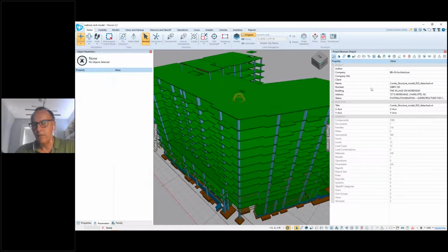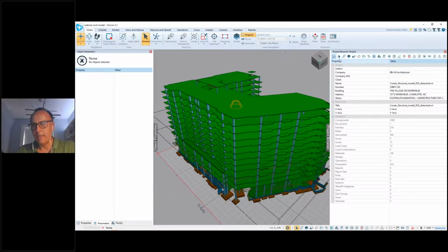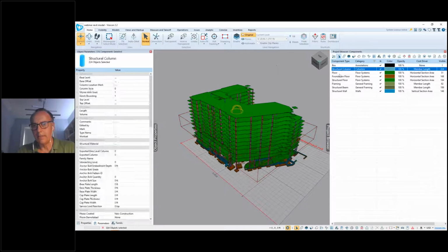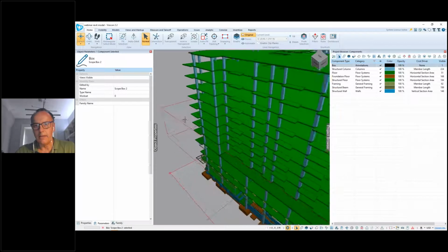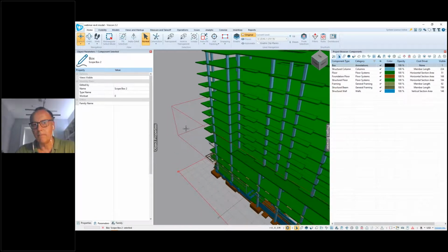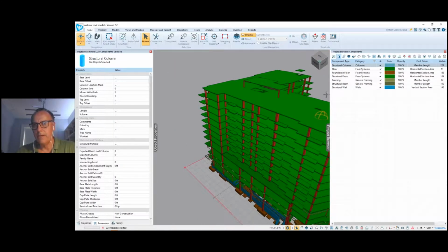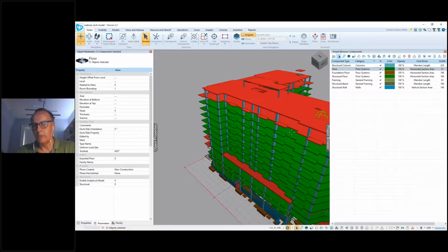On the right side, we've pre-organized your information for you to be able to quickly access the items. Here, I'm going to go to the list of components first, and I can just start selecting each of the various component types. Sometimes there will be things like these annotation boxes. If you don't want that in your model and you think it's getting in the way, just simply select the category and hit delete. So we're just deleting this box here. Now that's cleaned up, and I am left with just my primary structural components in this model.